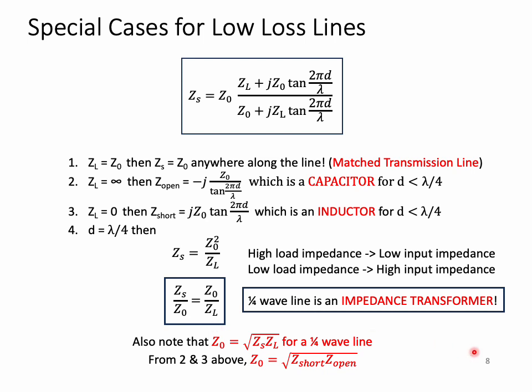There are a couple other equations that are useful to look at. One is when we have an impedance ZL at the end of the line and look at a quarter wavelength. For a quarter wave line terminated in impedance ZL, I can actually determine what the characteristic impedance is by measuring the impedance looking into that line. So in this case, Z0, which is the characteristic impedance, is equal to the square root of the impedance looking into the transmission line times the load impedance. So for example, if I put 1,000 ohms at the end of my piece of coax and measure the impedance looking into the piece of coax, if I take the square root of that product, I'll end up with a close approximation to what the characteristic impedance is.